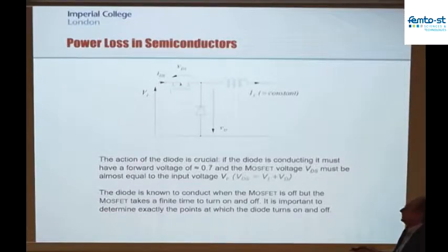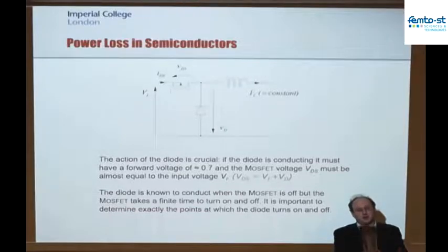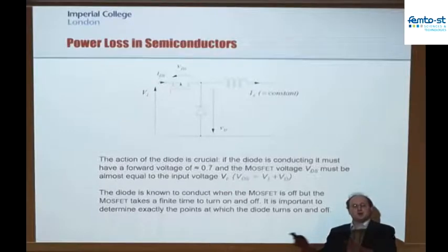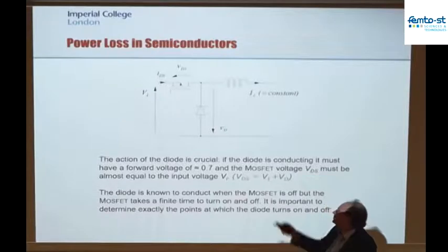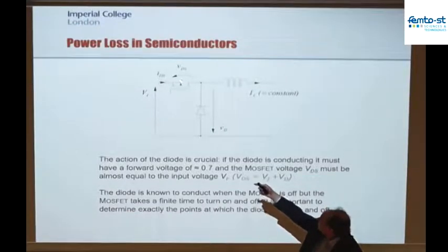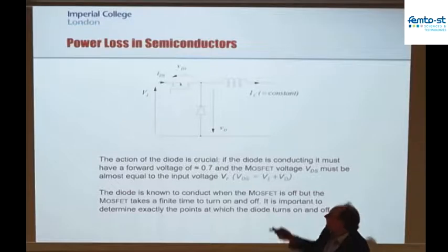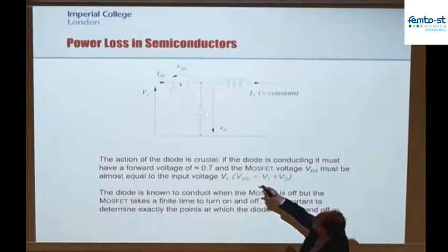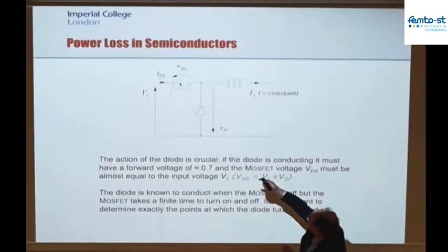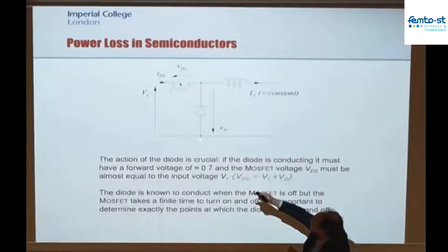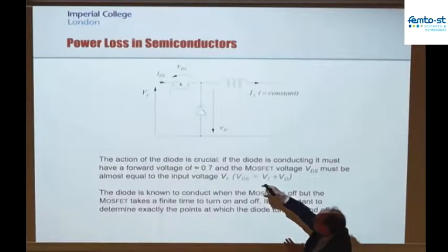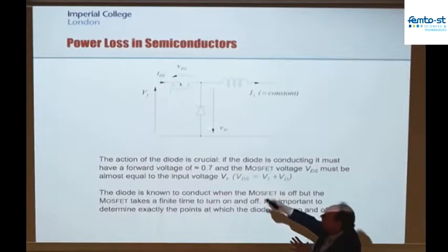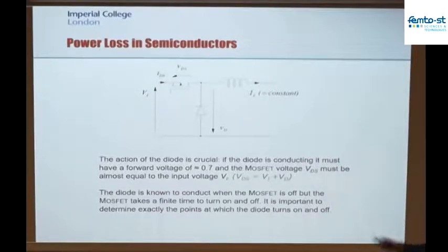So my switch mode circuit, which was operating beautifully with the transistor fully on and no voltage across it, or the transistor fully off and no current through it, and therefore theoretically an efficiency of 100%, now I start to look at the detail of the transition of moving the current from this path to this path, and suddenly I figure out that I could only commutate current from this transistor into this diode if the voltage at this point goes all the way to 0 first, whilst the full current is still in that transistor, even before I've moved any current into this diode at all. So that's fundamental. It means that I've got to have some switching loss.